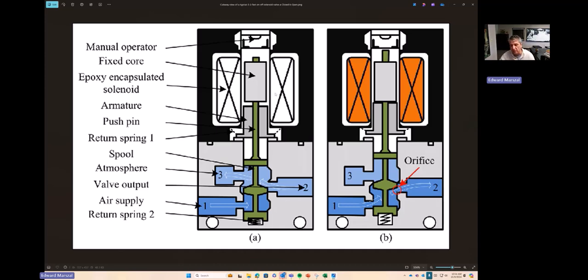Now, another mechanism could be that this plunger right here, when we're in the open position, gets stuck in place because I can build up crap. You like that scientific term? I can build up crap on the edges here that's going to prevent it from going closed. Well, how much crap I build up, and you could build it up here to prevent it from moving, kind of freezing in place, is going to be a function of the quality of your instrument air. The lower quality instrument air you have, the higher the probability that this failure is going to occur.